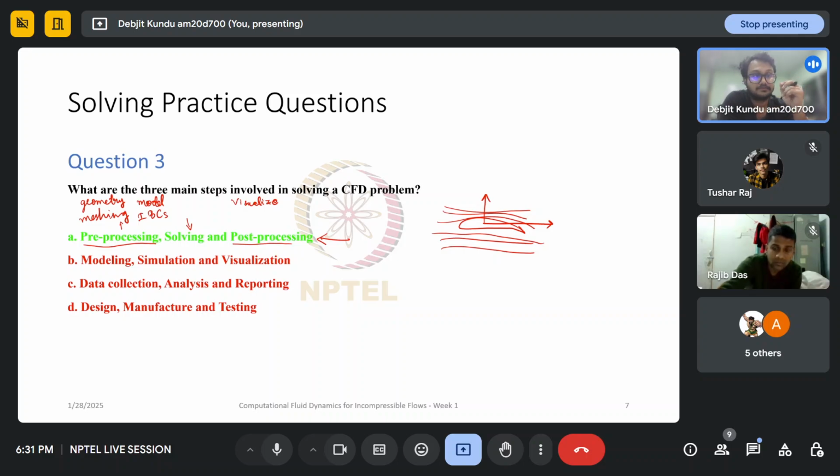Then, in a more detailed way, you might want to know what the shear stress distribution on this aerofoil is. Where is shear force more? Where is it less? That would determine some more design aspects of it. You might want to tweak the design wherever the shear stress is increasing, allowing more of those regions where the stress is less and so on. All of these things depend on your actual objectives, but this also falls under post-processing.